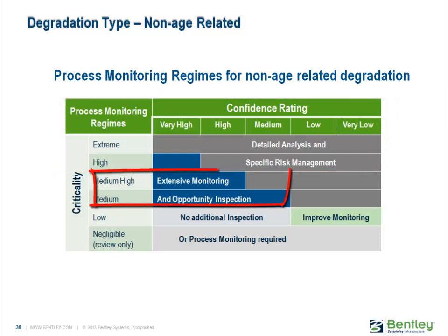For the average assets with medium or low criticality and high to medium confidence rating, we can apply an extensive monitoring strategy and an opportunity-based inspection regime to define the susceptibility of these assets to the degradations and failure.